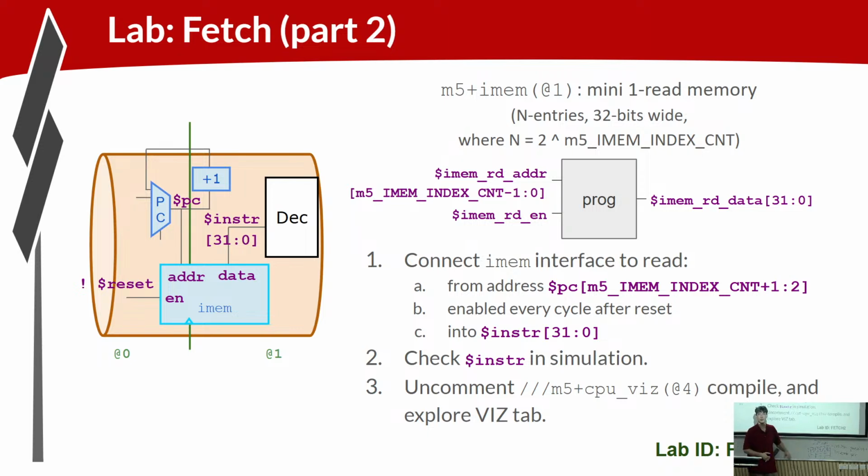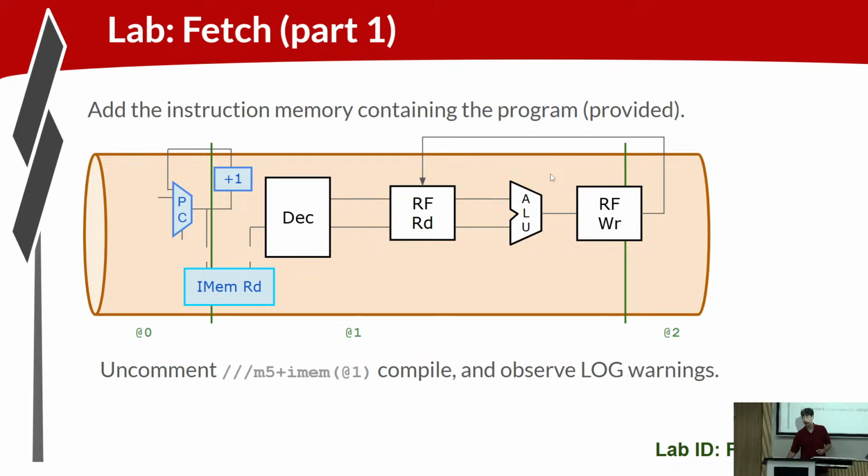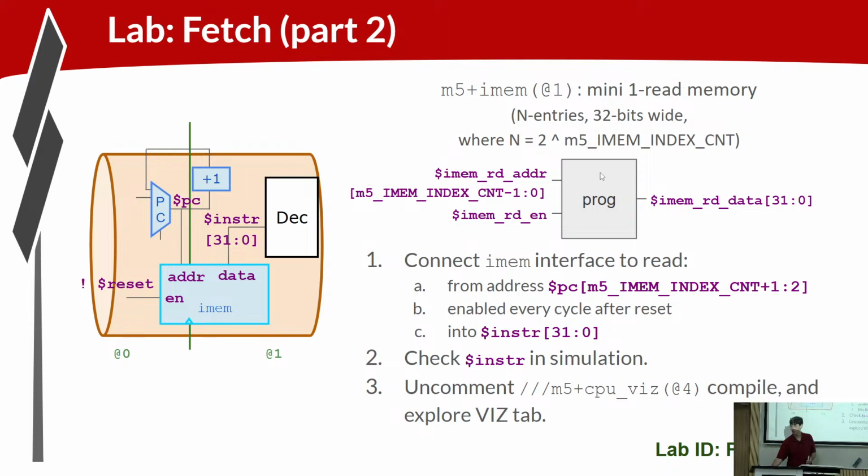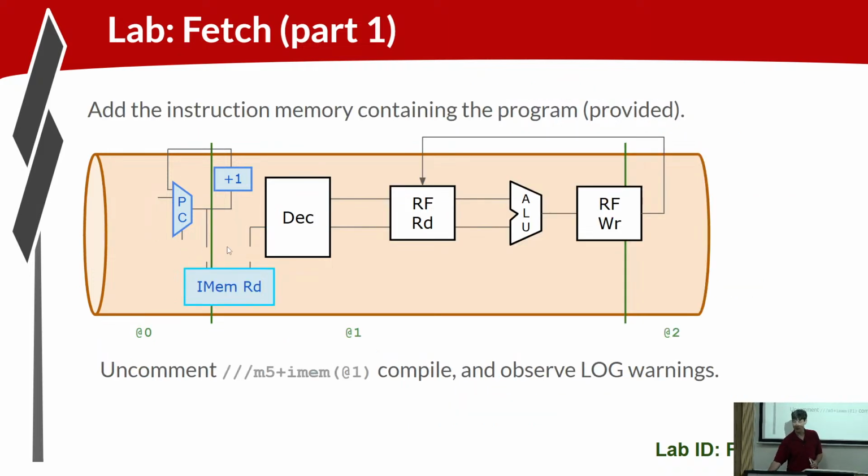The IMEM is a memory. It's done for you by that macro, right? So the first step here, uncommenting, or where is it? The last lab, where we uncommented the IMEM macro, that's instantiating the instruction memory, right? It's giving you this picture here. So at this point, we just need to hook everything up, right? When we instantiate it, we've got this picture with the disconnects.